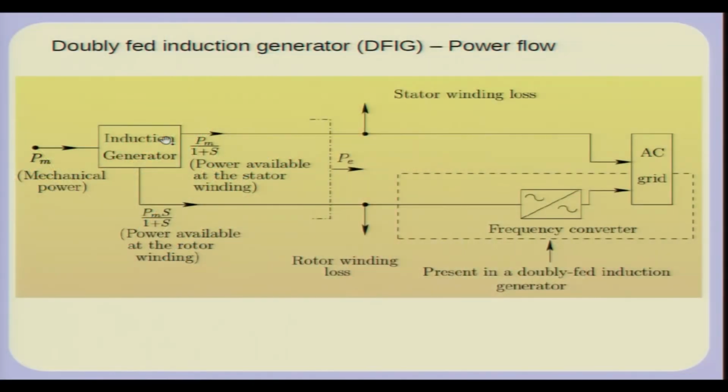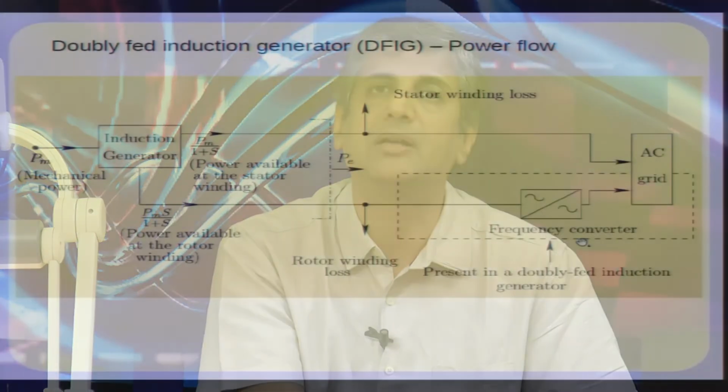So, you can actually change the characteristic of the generator. That is the thing you can take away from here, and once you change the power speed characteristic of a generator, you can change the intersection points with the turbine characteristic. So, the operating point may be as you would desire. That is the basic idea. So, this kind of controlled power extraction scheme is possible because of the power electronic converters.